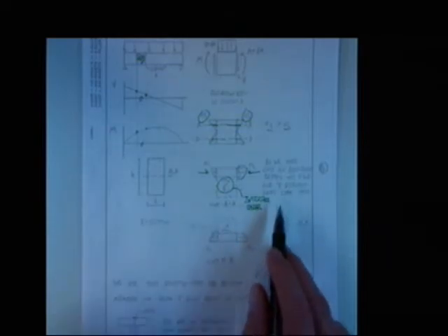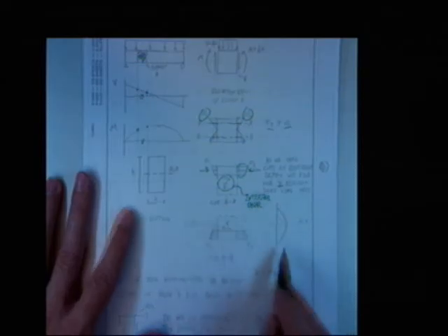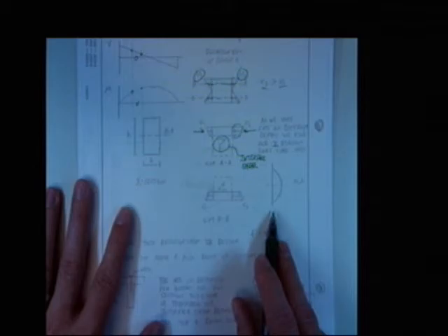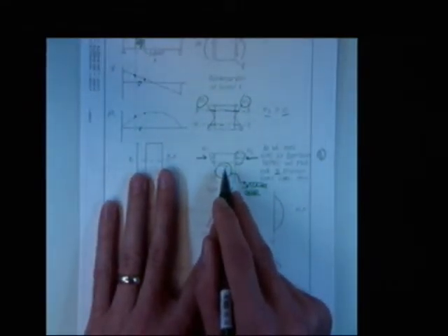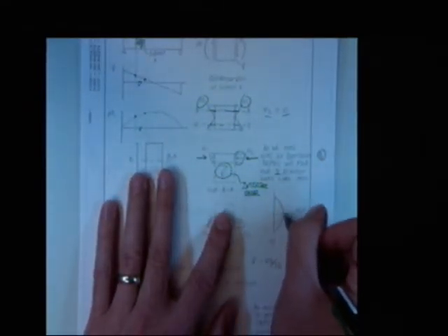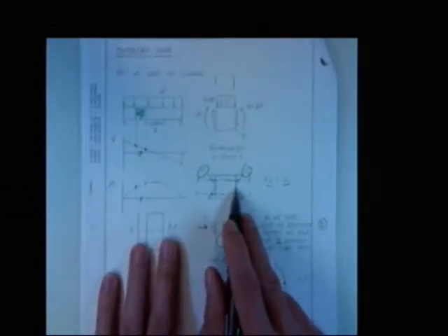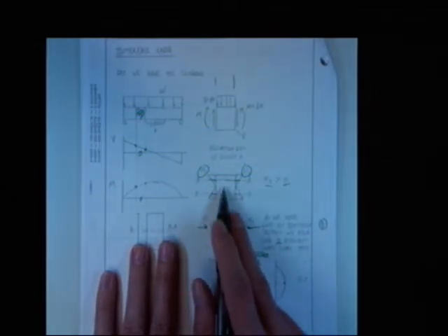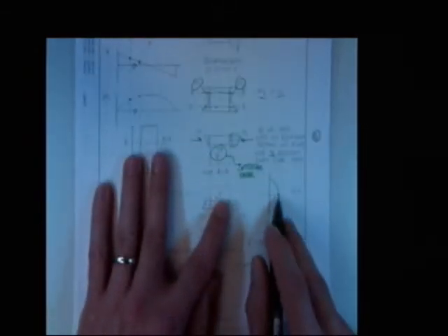As we take cuts at different depths, we find our tau diagram, our shear diagram. It looks like this. Whoa! That's what I told you to memorize. And remember, we just forgot why. We forgot that if we think about this force, this differential force, it'll be the maximum at the middle because that's where the maximum differential will be. Think about that. That's where the maximum differential has to be. Cross-sectional area is the same. Load over cross-sectional area is stress. That means the stress is the highest.